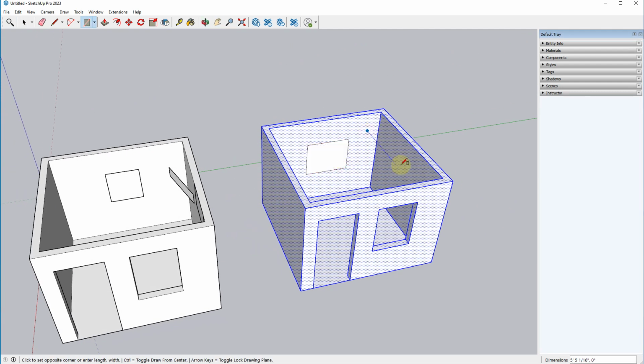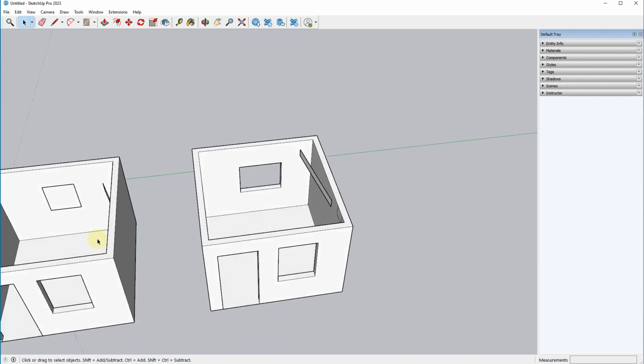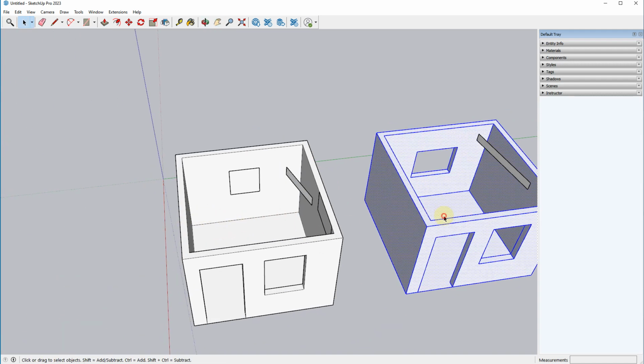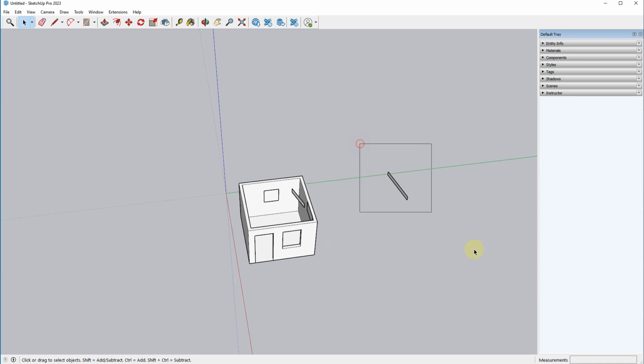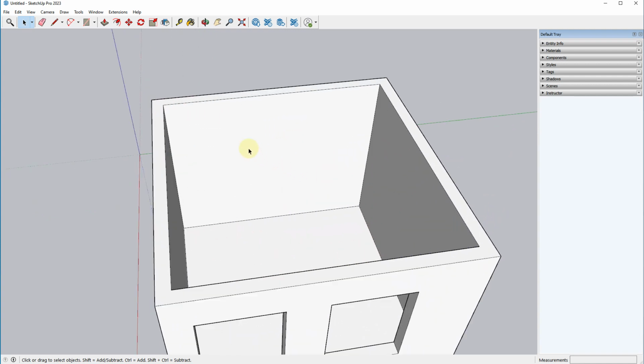If I start drawing on this like I did the other one, you can see that some of these surfaces are actually attaching here. They're creating new geometry as part of this, and I might not necessarily want another window right here, right? So as you're working through it, make sure that you group things, and this is something I mentioned to you guys in class. Make sure you're grouping things so that you don't accidentally intersect a cabinet with your walls.